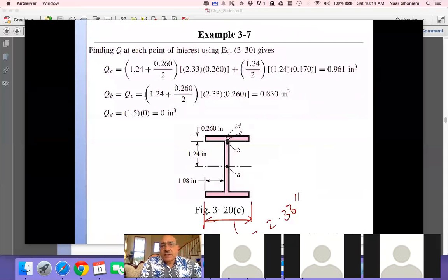All right, so the axial bending stress is easy, because it's M times C over I. So we found I, and then C is the distance to the top or to the bottom. But what we're interested in now is the shear. So the shear is VQ over IB. So let's look at Q as the critical element of that.